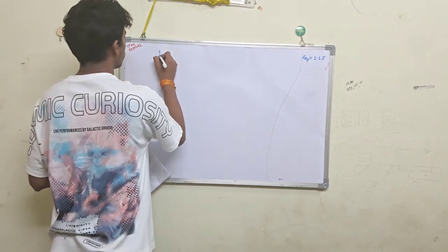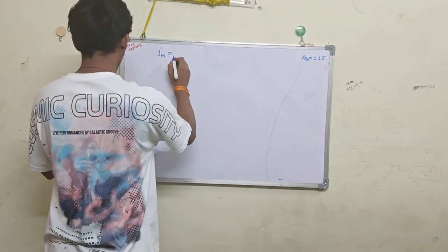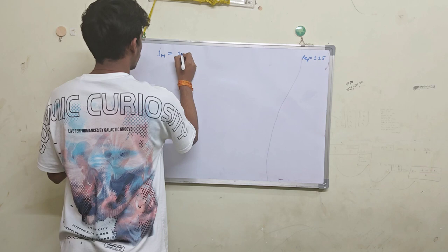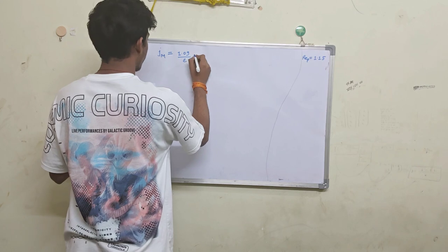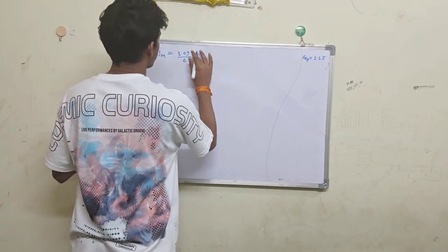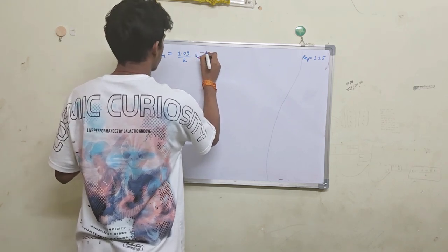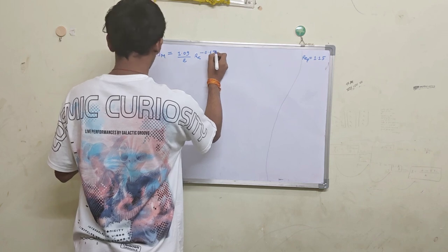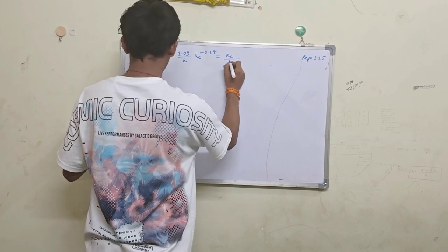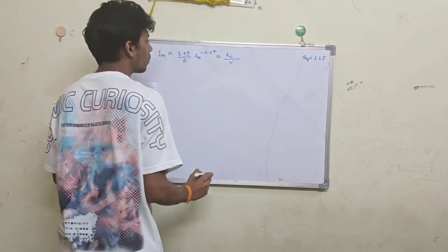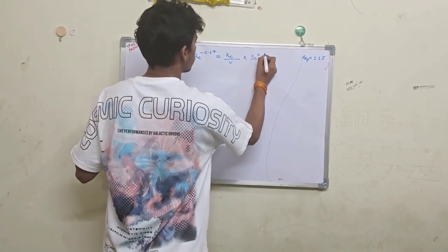So its formula is given as: Colburn factor for mass transfer is equal to 1.09 divided by void fraction, to the Reynolds number to the power minus 0.67, is equal to mass transfer coefficient divided by velocity, not volumetric flow rate, multiplied by Schmidt number to the power 0.67.